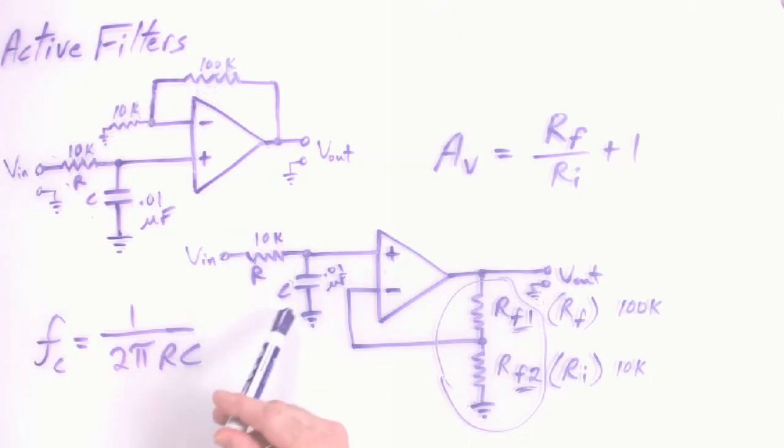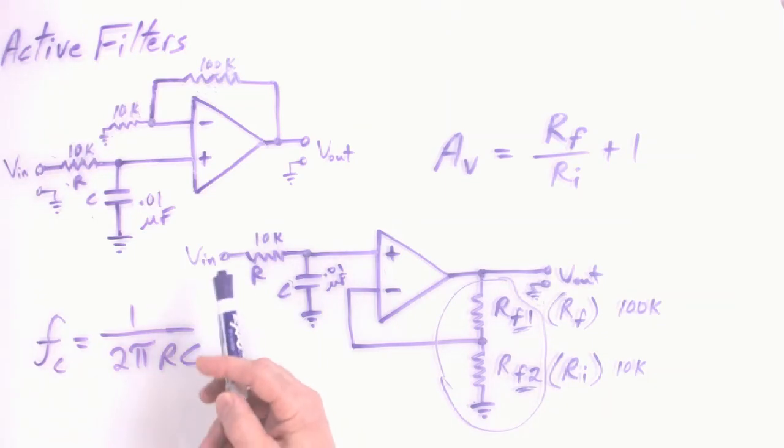Obviously, you can see, I think, if you reverse these positions here, you could have a quick high pass filter. And what we've shown in this video is just the beginnings. It is just to get your footing, and then off you go. There are, like I say, whole books on active filters and different designs. This would be the simplest design, of course, where you just have a single pole doing its voltage divider thing.